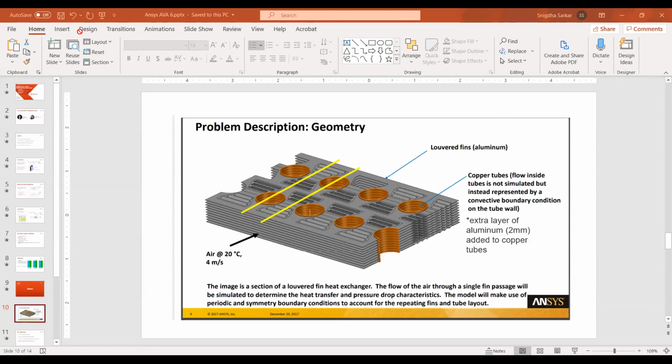But shell conduction doesn't really account for porosity. If you had the equivalent thermal conductivity for that layer, perhaps that would work. But when I actually show you the setting up of shell conduction, you'll see what inputs we can define within Fluent. So I hope that answers your question. And if you had additional questions about how to set up heat transfer in a porous region, please feel free to reach out. I'll include my contact information at the end, and I'll be happy to answer that question at that time.